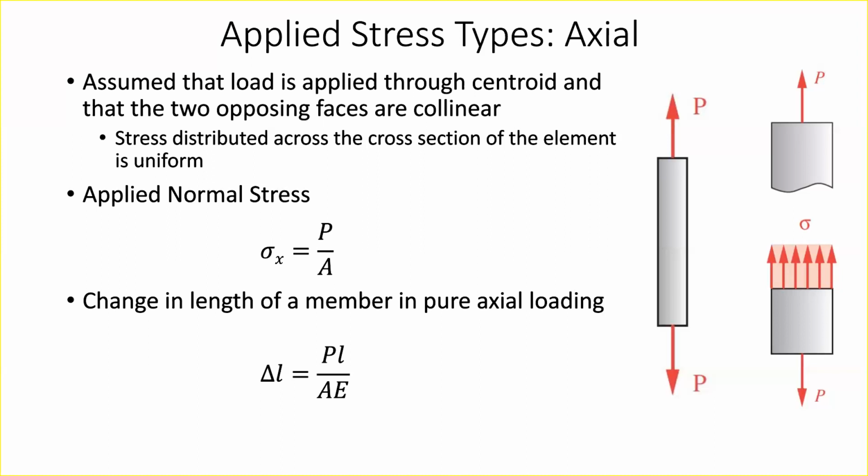For example, the suspension control arms on our vehicle are really just loaded in tension and compression because of the unique way they're constrained. So for the most part, you can predict the failure of a pull rod with just one equation, which is pretty crazy. But again, these fundamentals go surprisingly far.